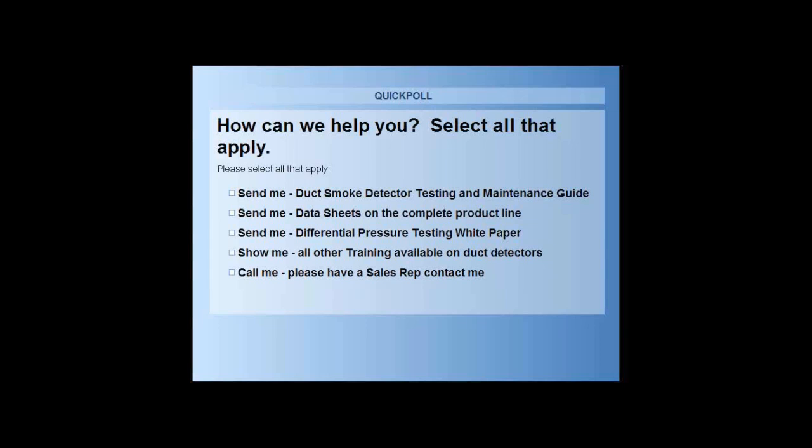Okay. All right, very good. Next question deals with dry nitrogen, and they're asking if they can clean a duct smoke detector with dry nitrogen. Yes, you can. Cleaning a detector with dry nitrogen should work perfectly fine. Most of the time I hear people using either a little vacuum or canned air, but dry nitrogen is perfectly fine to use also.